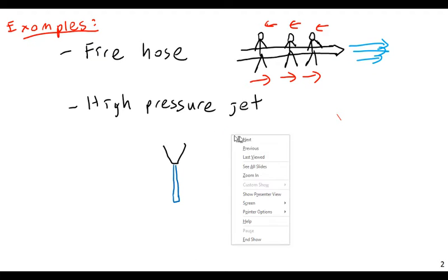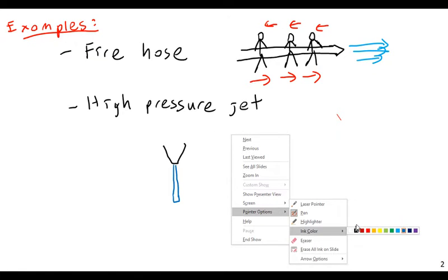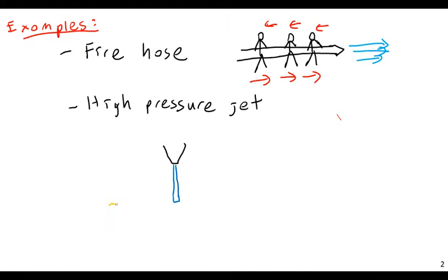And what that allows you to do is, when this incredibly high pressure jet of water strikes steel or metal or any really other surface, it can cut it. It can cut right through it and form a very clean cut. And this is very useful for certain different types of materials, especially materials that are prone to heating when cut. The nice thing about this is you don't need any kind of cutting fluid.